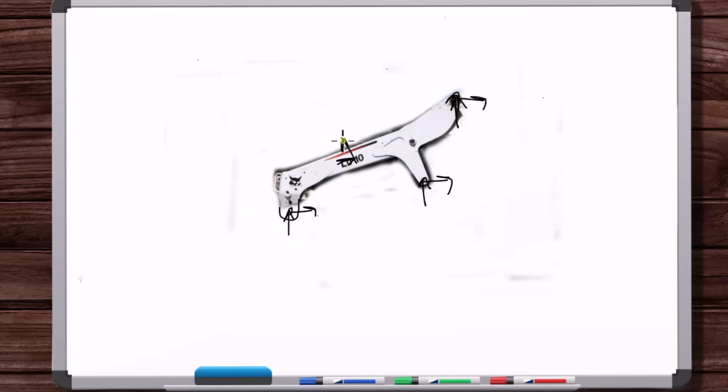Because if I'm going to do that, well, then I can put the reaction forces here and here and here and here and here. That doesn't make any sense. But there's a pin here, right? Don't we need to... there's forces in that pin, right? No, the forces in this pin are internal forces as well. This is a rigid connection.